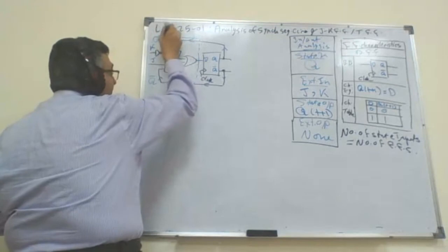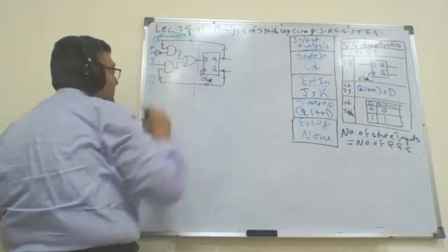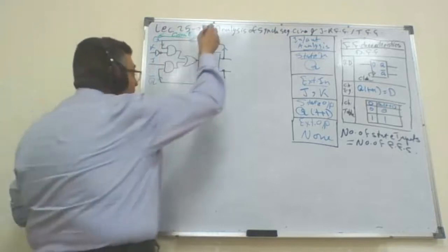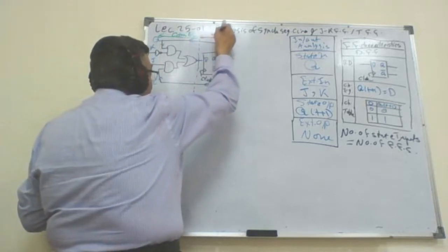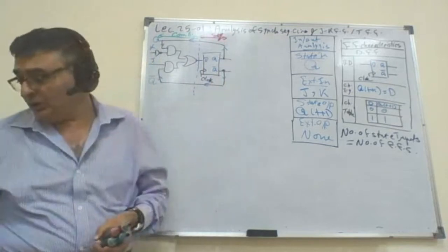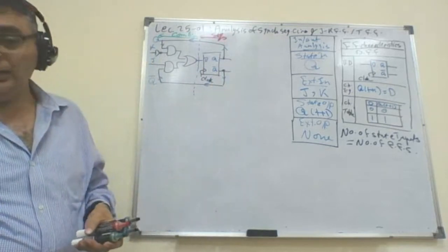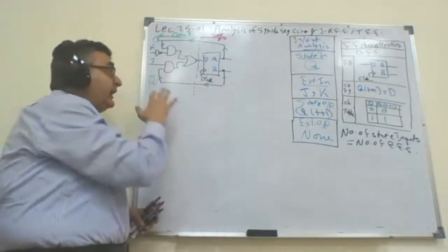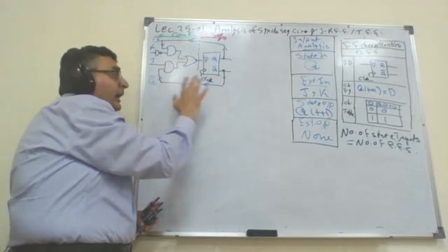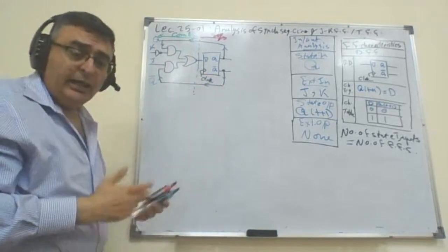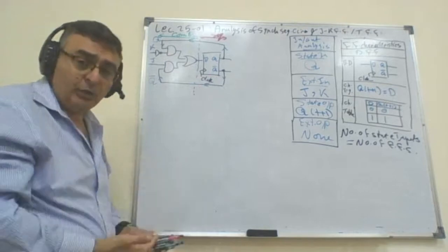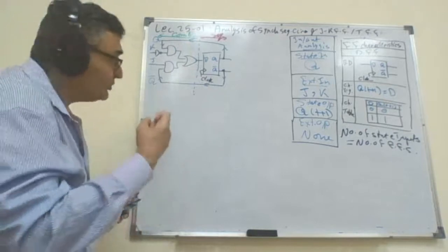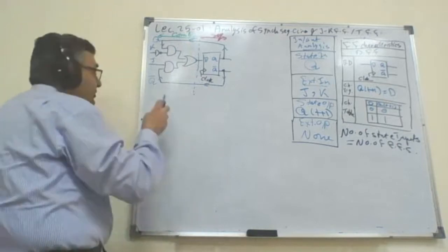This part is the combinational side of my circuit. This part contains only the sequential circuit, which is the flip-flop. Now, since I split the circuit, forget about the feedback, analyze the combinational part alone and the sequential part alone, and you can easily derive the equations and just substitute them into each other. You will get your first requirement, which is the equation.